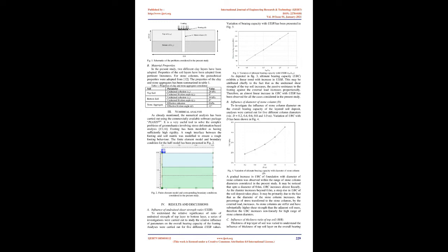The lateral and vertical boundaries are selected such that the stresses generated during loading are well confined within the boundaries of the problem. In the bottom boundary, both horizontal and vertical fixities were applied while lateral boundaries were restrained in horizontal direction. A fine mesh refinement was adopted based on a mesh sensitivity study.